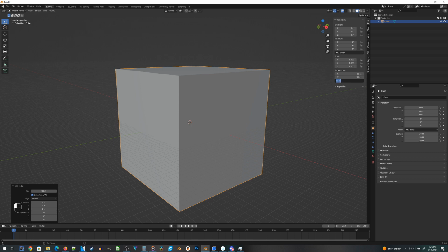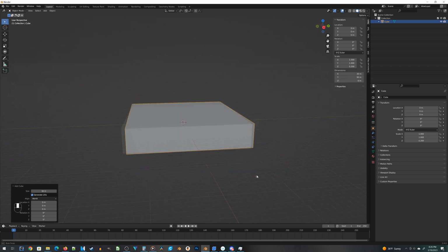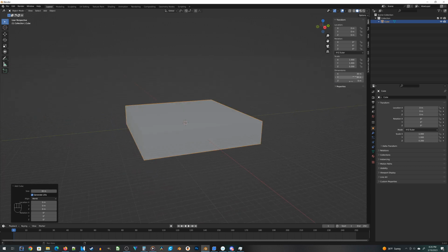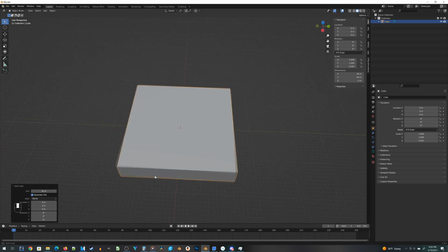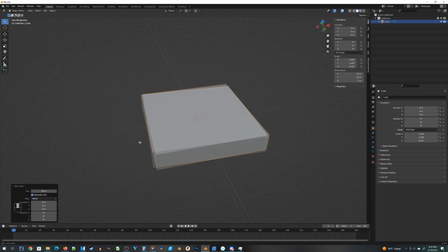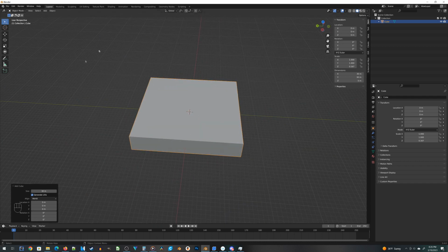So let's click on Z and replace the 30 with 6, or 6 millimeters, which is about 1/4 of an inch. I'm actually going to go ahead with 5 millimeters, make it just a little bit thinner. And the last thing I want to do is name this object as the base, so I know that's what it is. Over on the right-hand side of the screen, you have a whole bunch of more control buttons. There's a lot of those in Blender.